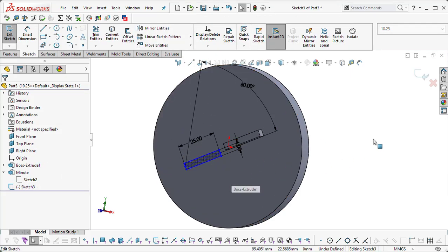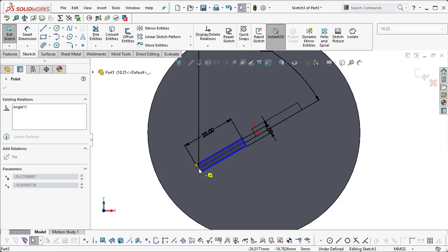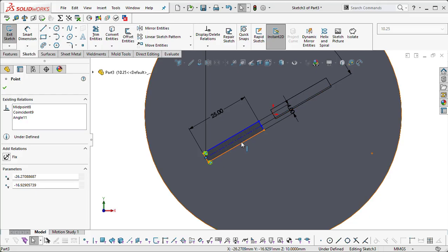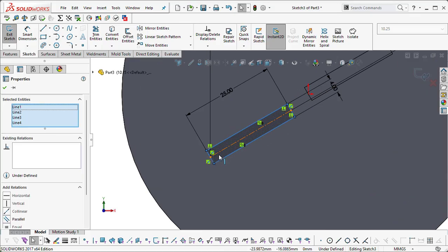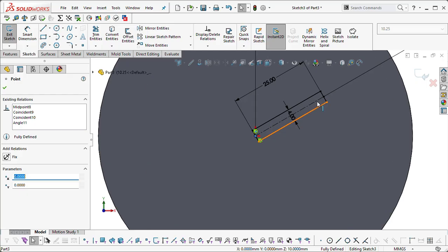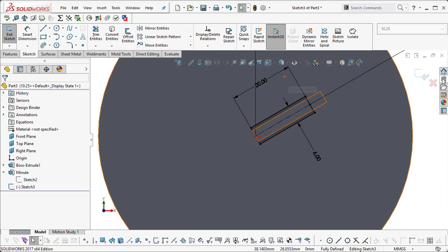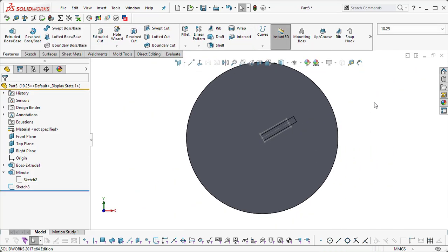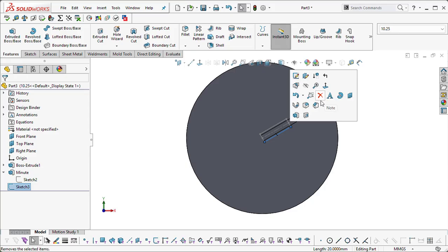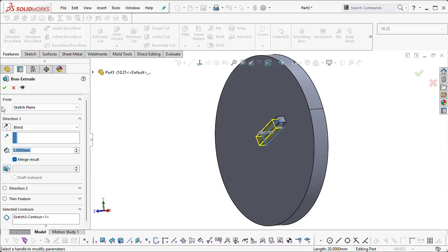Edit the sketch. Let's go normal to. All you want to do now is drag this point, since the whole thing, oops, that seems not to be connected. Since everything's being brought through, just drag that point back on there, and then we can change the dimensions so that this is 6 and that's whatever, 20. This is for illustration purposes only, and then you can extrude that. So extrude, see, that is 5 mils, that's fine.